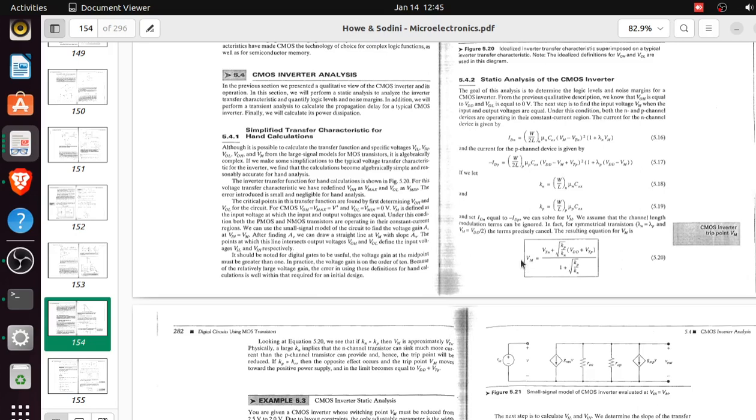You can see that VM determines what is fundamental about the digital CMOS inverter. We know about the on and off, the ones and zeros. It determines how well the digital device will give you the one when it's supposed to give a one, and the zero when it's supposed to give the zero. So VM determines that through the noise margin, and indirectly it's affected by these electrical parameters. Another reason to appreciate the whole theory you have done so far in the course. That's why we needed to know about the mobility, the capacitances and all of that.